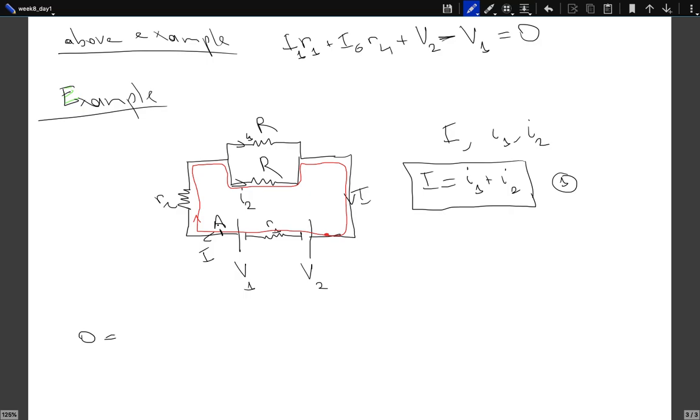That's my point A. Now I'm crossing a resistor. What is the potential drop? Well, the current running is I. The resistance is R2, so the potential drop is I times R2. And I know that the current always flows from a high potential to a lower potential, so there's actually a potential drop here. So that's why I don't introduce a minus sign there.